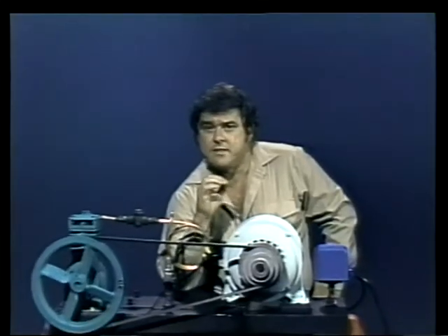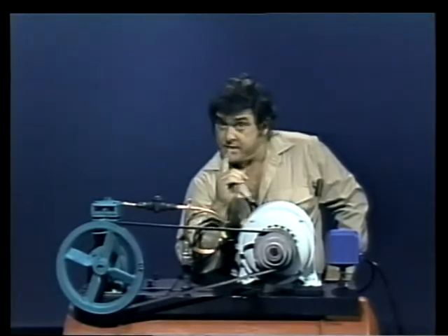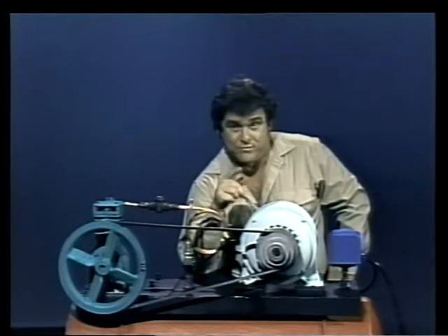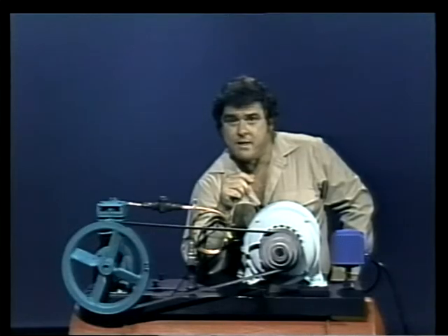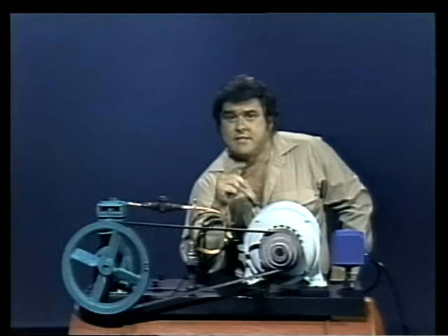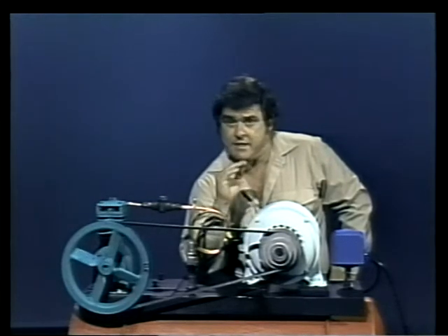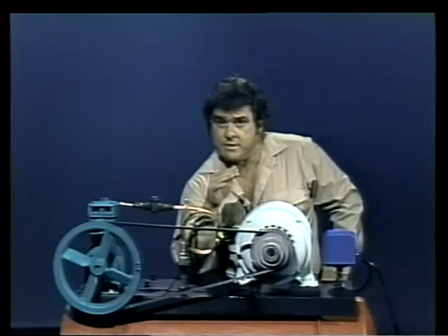The other compressor we've seen in this section, the liquid ring type, is also very different from other positive displacement compressors. It's different because water acts to squeeze the air into a smaller space. Its other main difference is that it has only one major moving part, the rotor. That makes it the simplest and the most trouble-free of all positive displacement compressors. Keep these differences in mind as you read Section 4 of your text. It has more detail on the components and the operation of liquid ring compressors and rotary blowers.